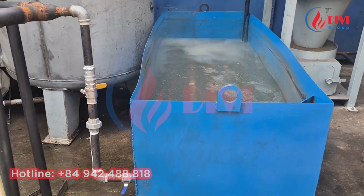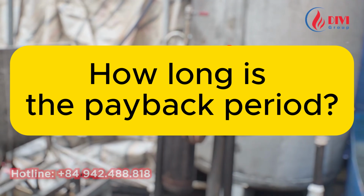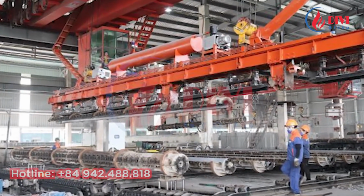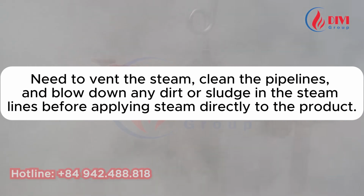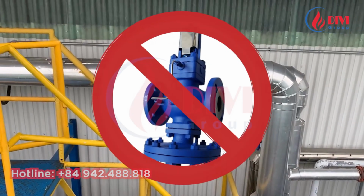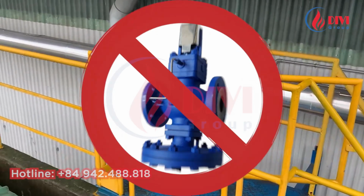Next, we will move on to a very important analysis. How long is the payback period if we install this device? If a factory uses steam directly and water content in the steam is not a critical issue, for example, concrete pile curing plants or steam bun production, then installing a steam separator is not necessarily required. For the food industry, you simply need to vent the steam, clean the pipelines, and blow down any dirt or sludge in the steam lines before applying steam directly to the product. In cases where the steam from the boiler is already dry, the steam pipeline is short, and there are no pressure regulating valves or special control valves, then installing a steam separator is not really necessary.